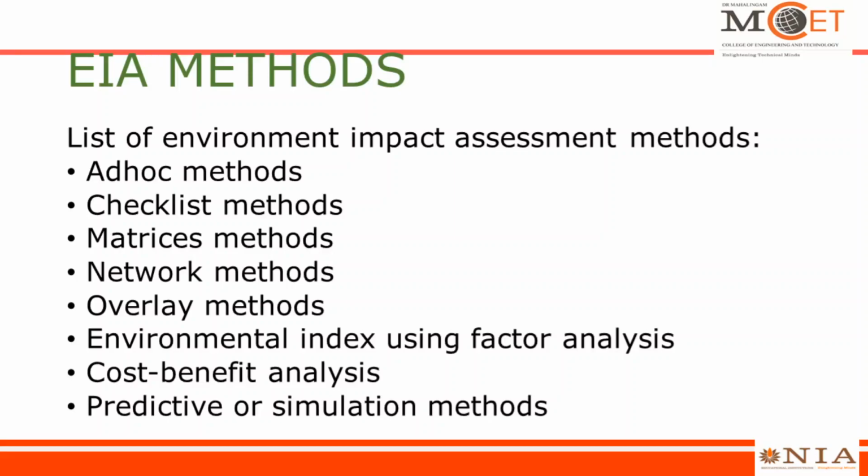Why? Because simply knowing where the wells are, you may not know how to recharge them. You'll have to know the soil type. For example, a well may be there, but surrounding those wells may be rocks, so water is not going to penetrate into the aquifer or the regions below the top surface. Water will not go down. So you need to know the type of soil located near the wells. That is why we have taken the soil map.